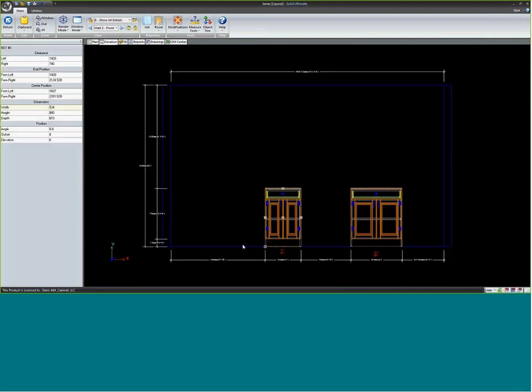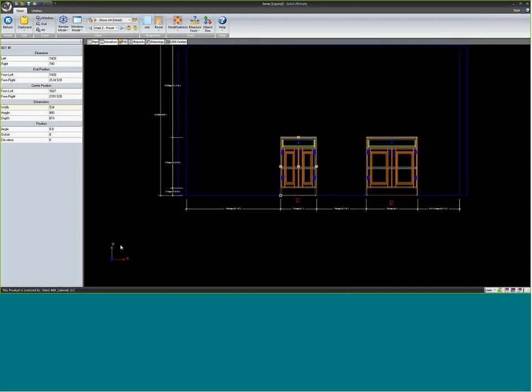If I go to elevation view and click on one of these cabinets, in the y direction, if you're using your right hand rule, y is up and down. Your index finger is sitting at the very bottom, so it's at the 0 point, so its elevation is 0. If I change its elevation to, say, 500, it is 500 positive in the y direction.